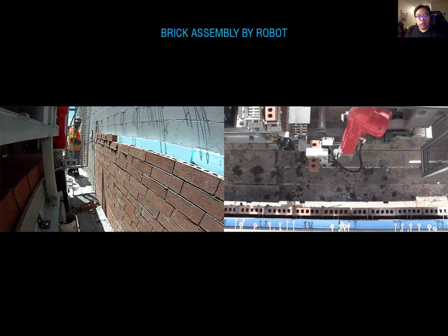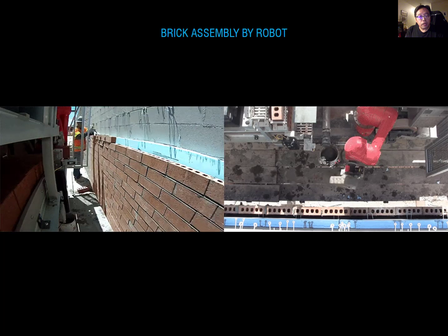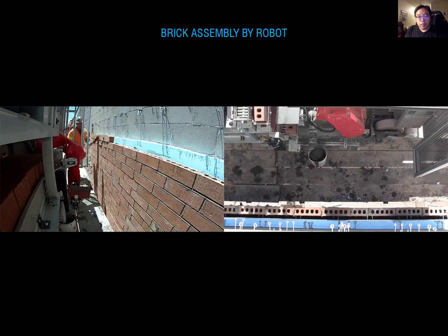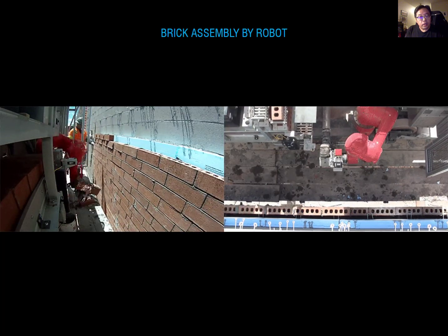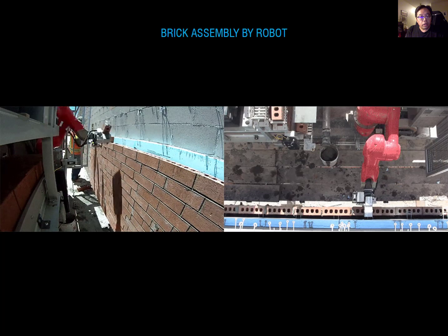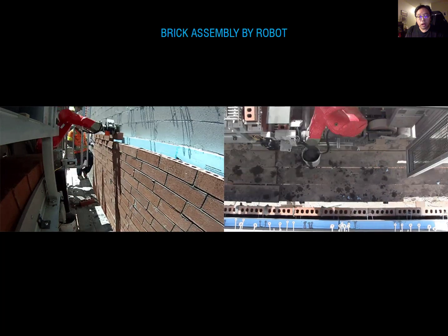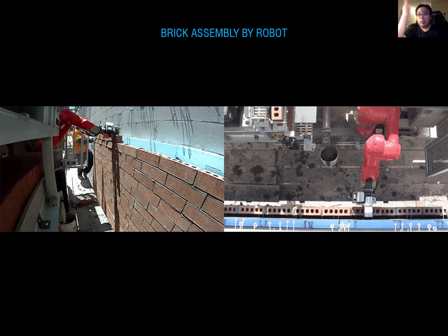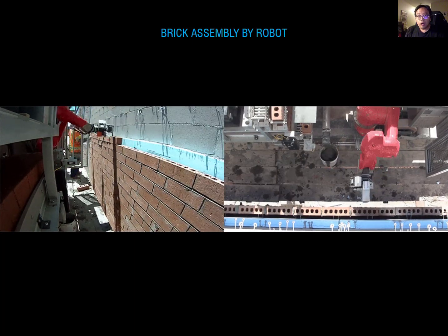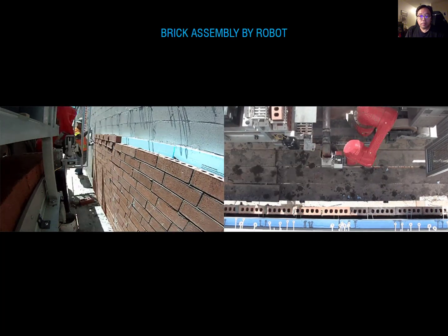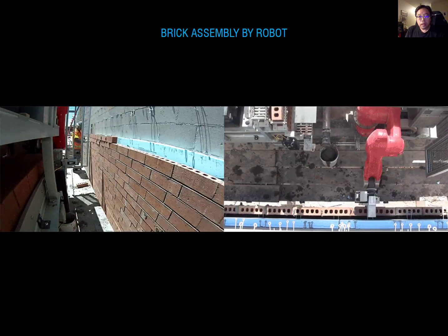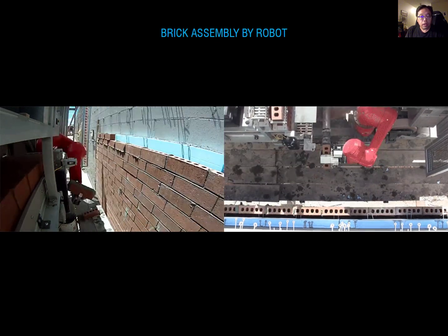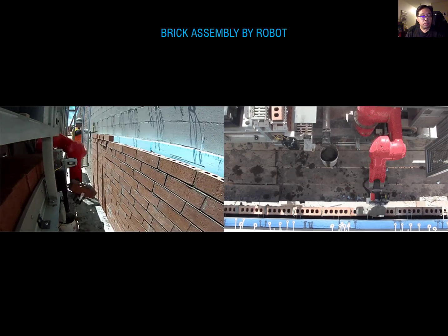Okay, and then you can also see this brick-laying robot. This robot's name is SAM, the semi-automated mason. The robot consists of a standard 6-axis industrial robot arm. 6-axis means it can move along the X, Y and Z axes, so the robot arm can move anywhere. They use the 6-axis industrial robot arm mounted to a conveyor belt. It picks up each brick, covers the side with mortar, and places it next to the last brick.